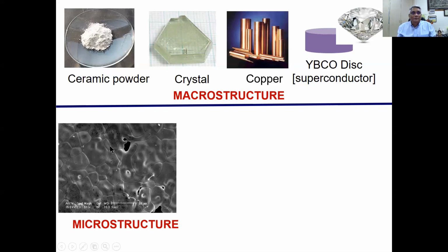Because when the current is flowing through this, current always flows through the least resistive path. And in this particular case, for the current to find the least resistive path is not a problem, but here it has to encounter the grain boundary energy. So that means the current has to even tunnel through these grain boundaries. But if the grain boundary widths are too large, then there's no way current can tunnel through. So obviously, the resistivity measured in this case will be enhanced because of the contribution from this grain boundary resistance, and versus having these voids.